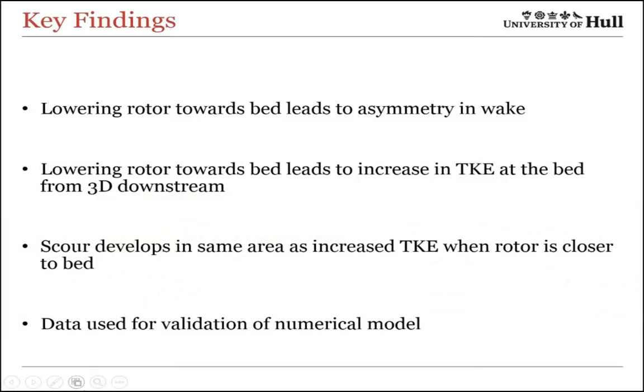So, to summarise, some key findings to take away from the brief talk today. Thinking about lowering the rotor to the bed, how it impacts on the asymmetry of the wake, what that lowering and the asymmetry does in terms of turbulence kinetic energy, the patterns of turbulence in the lee side of these rotors, and ultimately what they do in terms of sediment transport and scour in the lee side of these sorts of features. And as I said, it's part of a much bigger grouping who are then using this key data that we've been able to get from our physical experiments to put into numerical models, which obviously allow us to scale and generalize much more capably than we can within a suite of experiments in a flume.